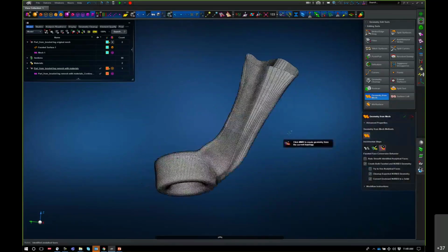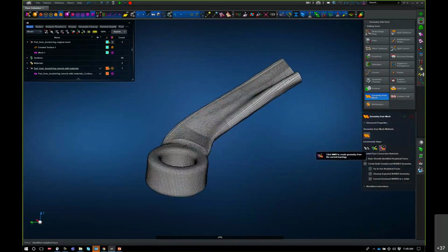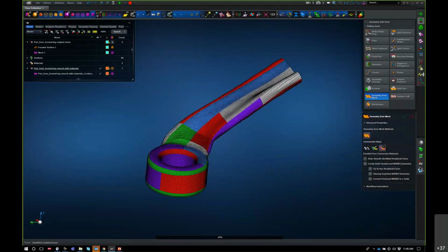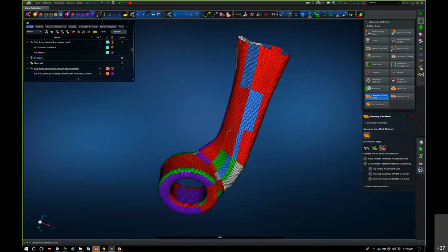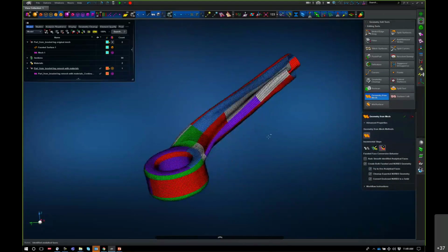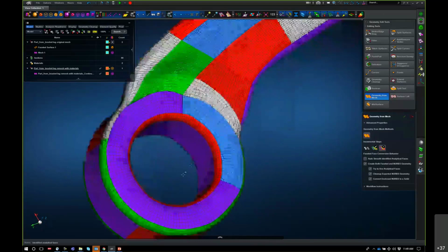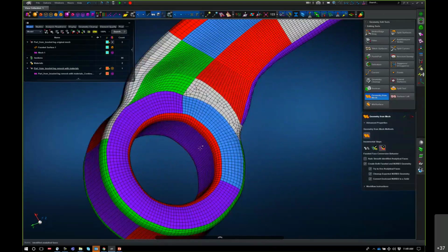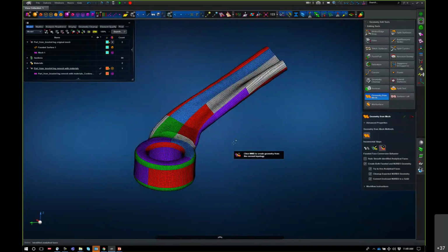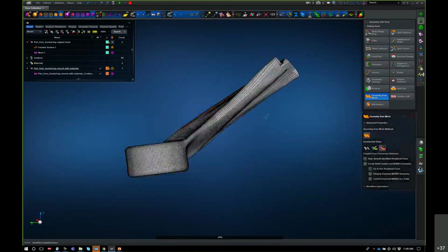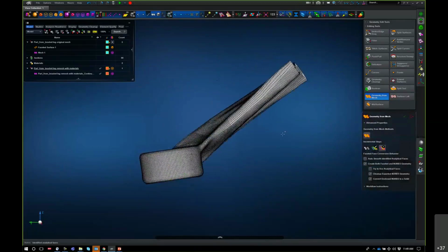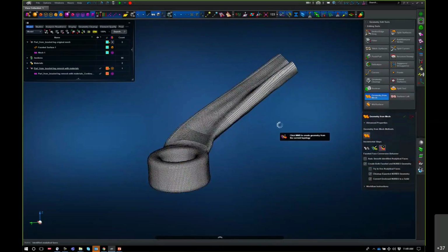Smoothing, and have it convert, because the smoothing is actually going to convert. Try to smooth, the shapes aren't really here. Typically, when you have an organic shape like this, it has no real shapes. These aren't real shapes in here. This is not a real cylinder. The tolerance is a little too coarse because when I imported it, I forgot to pick inches. So once again, for organic type shapes, you would leave it off the conversion.